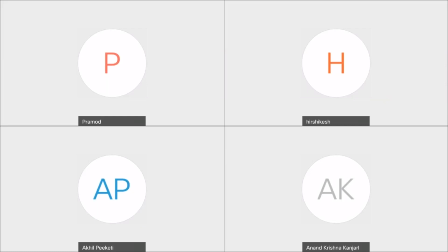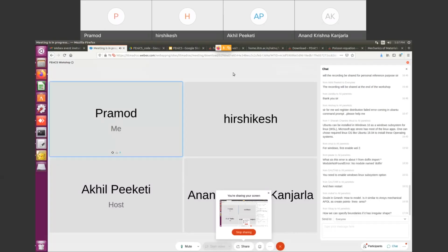We can get that from either the inbuilt mesh software, which has the primitive shapes in place. But if we need really complicated shapes, as someone was asking, splines and everything, then one resort is GMSH. From there, we can convert the meshes from MSH to Dolfin readable format. That is what Rishikesh showed.